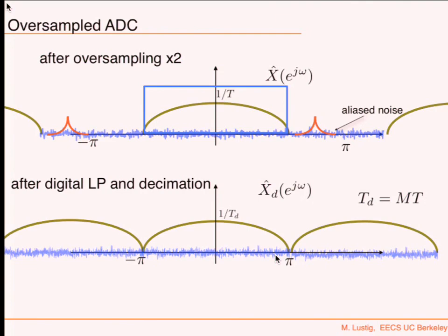Sorry, could you clarify what's the difference between quantization and sampling? All right, sampling is taking something continuous and evaluating it at a discrete number of points. But the representation of that could be continuous, infinite, like a continuous number. But then I want to store it on a computer. Let's say I'm going to store it in 16 bits, 32 bits, 64 bits. Pick your precision, but it's going to have a certain precision. So that precision is limited.